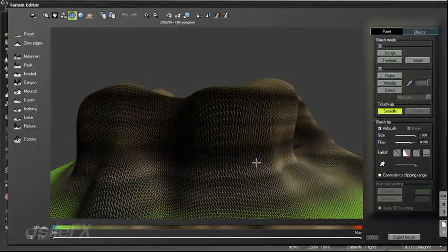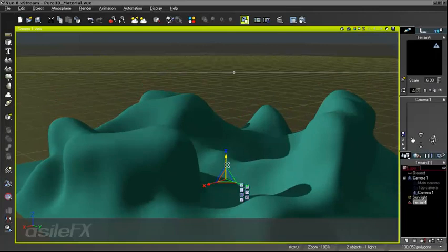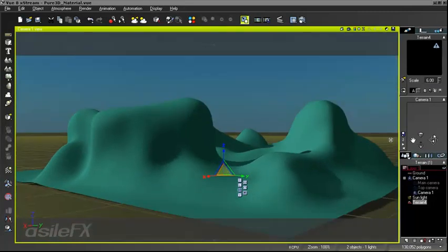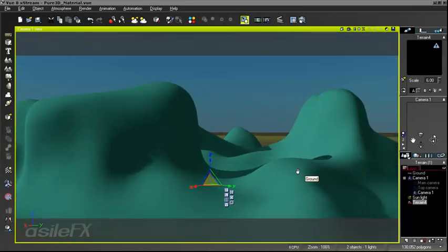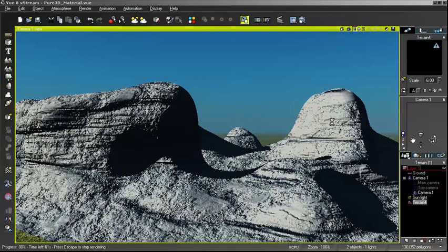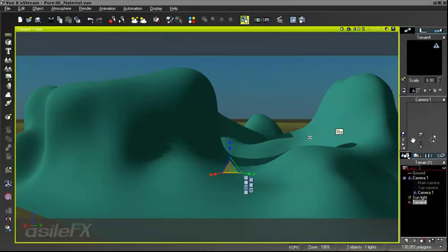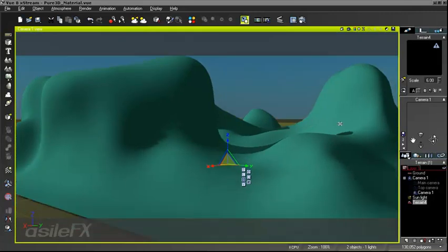And what we really want to do is displace the horizontal direction rather than the vertical direction, because otherwise we could just be using a regular terrain and not even have to worry about displacement mapping. So what we want to do is set up first just this bump. Not having displacement mapping on gives us a much quicker render and a very easy way to tell exactly what's going to be displaced.